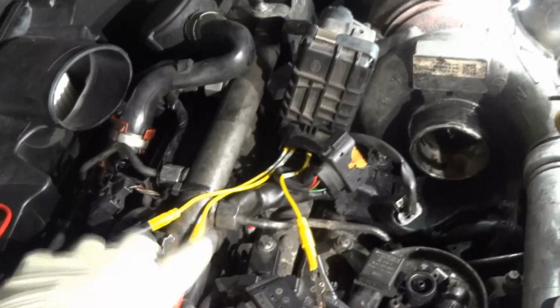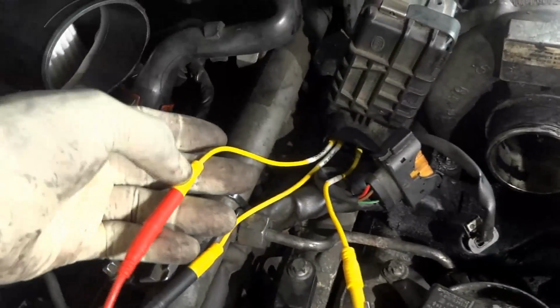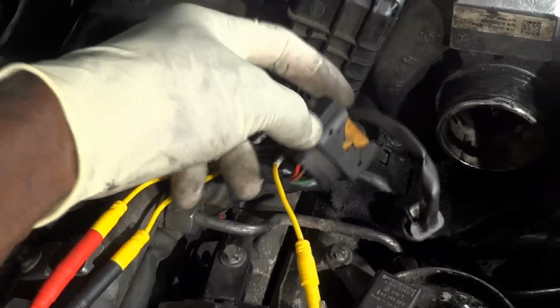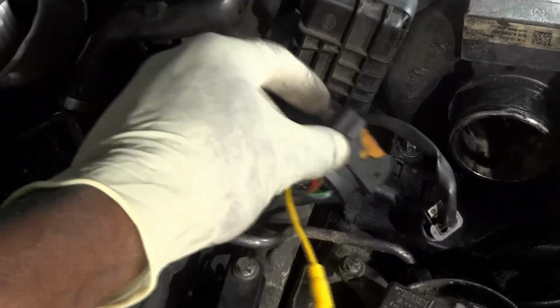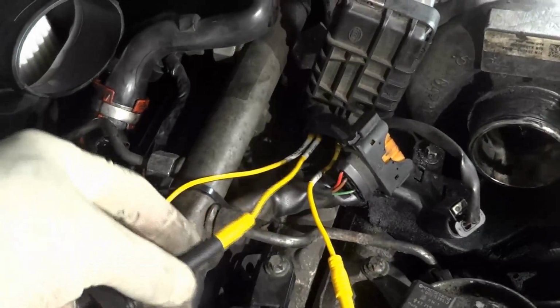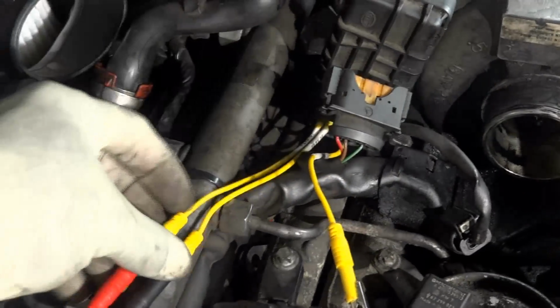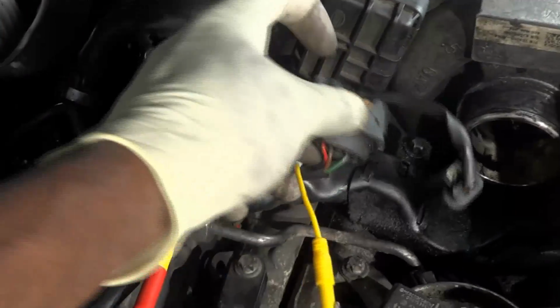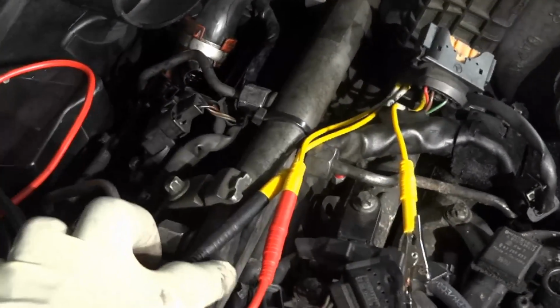So here's what I did, guys. I am energizing this actuator manually. So I'm sending power to it because this is a constant power. So I'm actually bypassing this wire here on the connector. So I'm sending power to it, okay, power. And then the brown wire, which is a ground, okay. So just look at it this way. I'm just bypassing these wires, okay. So power, ground, and then the third wire, which is this one, is a ground coming from the computer, okay. So I have power going there, ground.